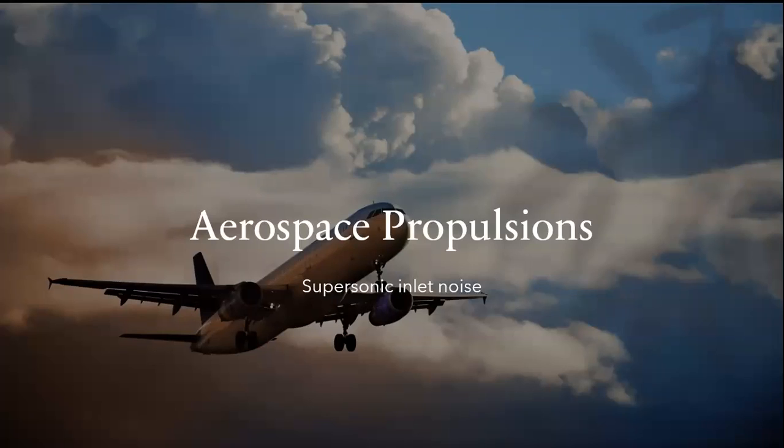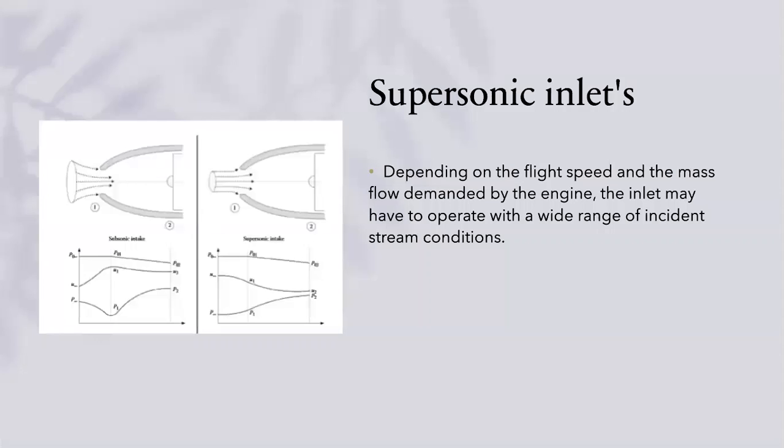Now I'm going to talk about supersonic inlet noise, related to the course of aerospace propulsion. Supersonic inlets, depending upon the flight speed and the mass flow demanded by the engine, may have to operate with a wide range of incident stream conditions. So these are the two stream conditions, that is, subsonic intake and supersonic intake.